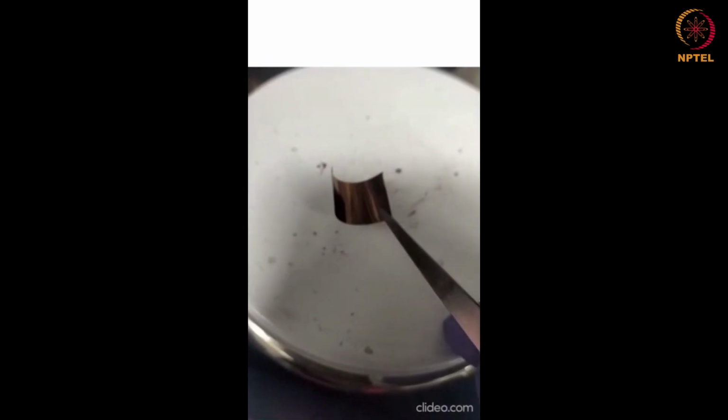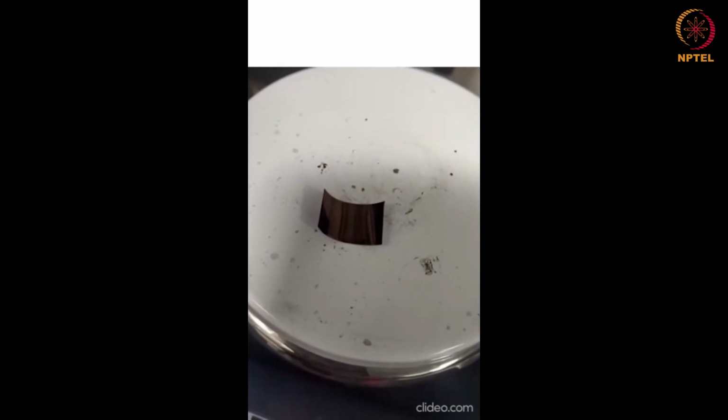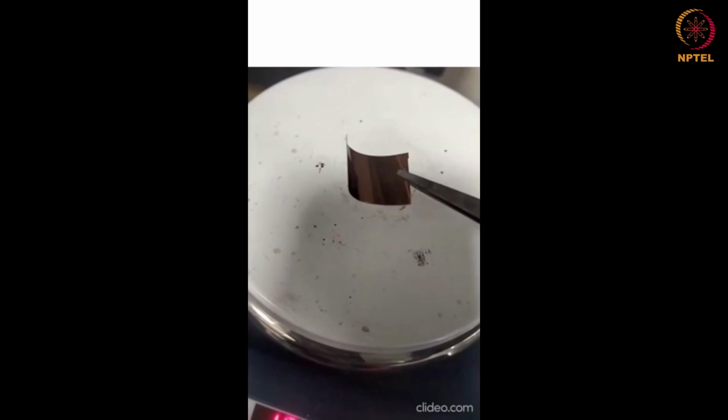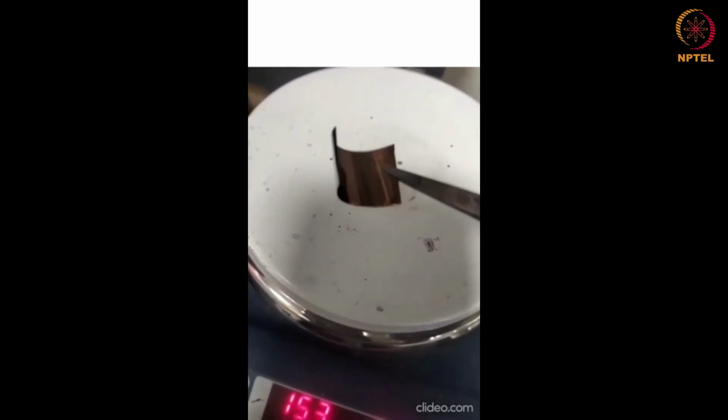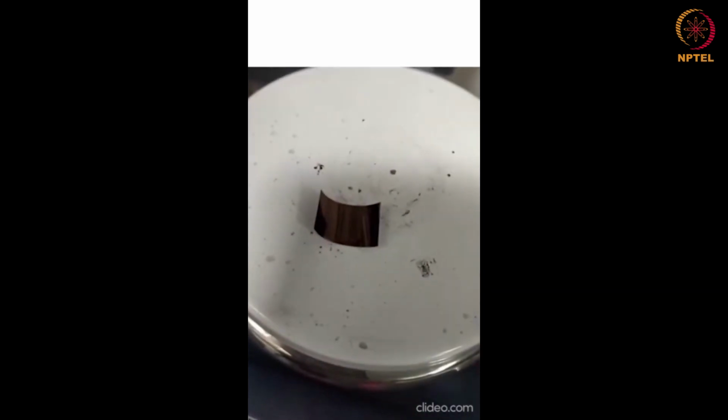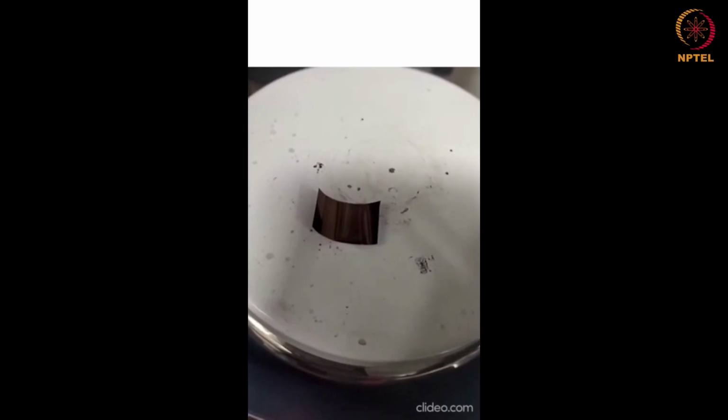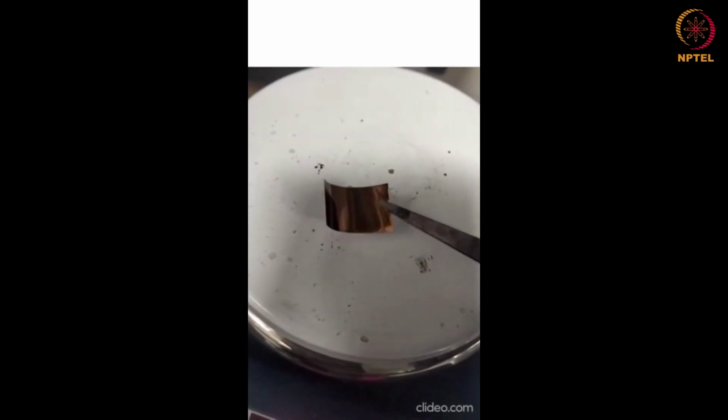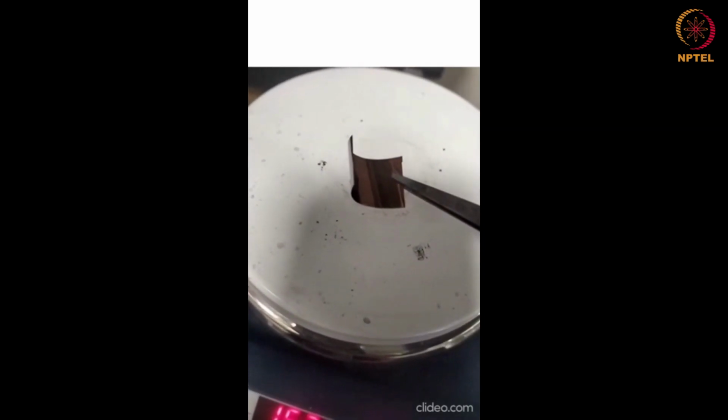The thermomechanical actuation of Bimorph can be tested on a hot plate. During heating, it expands because of the austenite phase, and while cooling, the phase retention happens. This phase transformation behavior was observed in the window of SMA between 80 to 120 degrees Celsius.